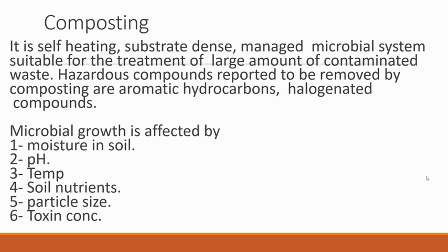Okay, what actually can affect composting? The same things. Moisture, if your compost is dry, degradation will not take place. So moisture content is very important, pH is very important, temperature is very important, soil nutrients are very important, even soil particle size is very important, and also the concentration.